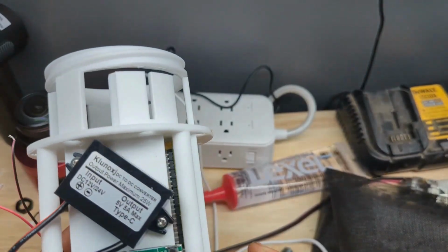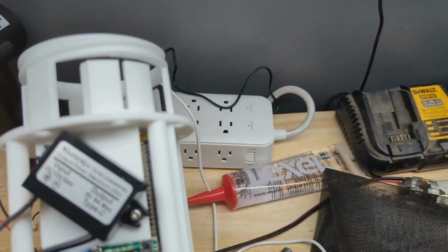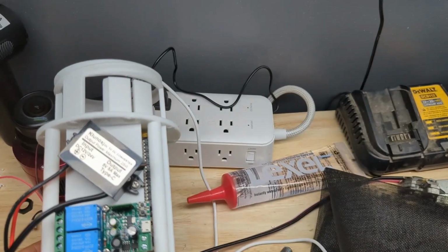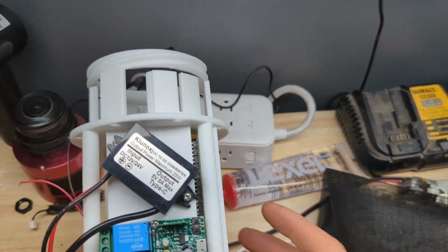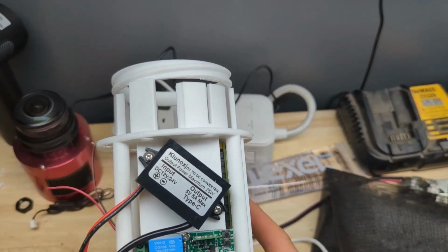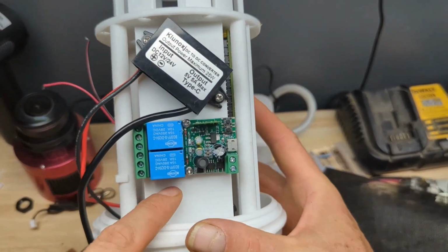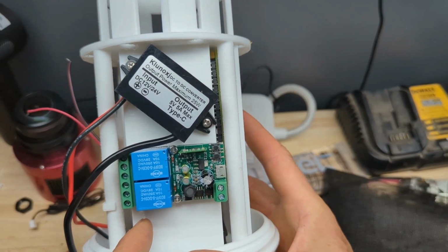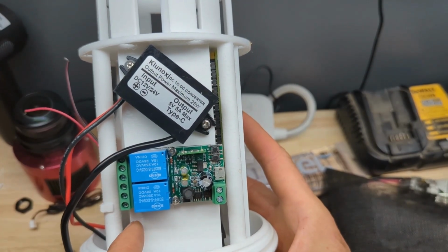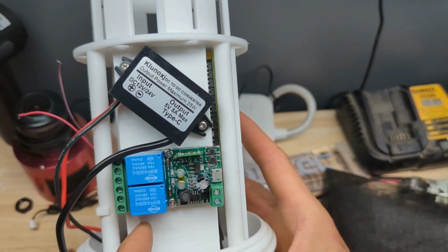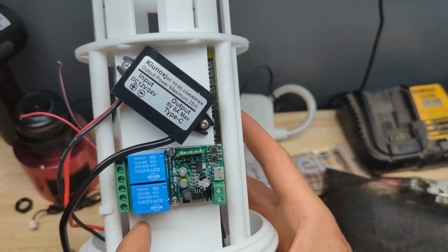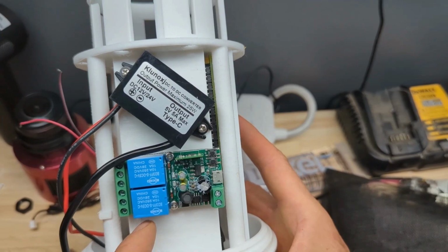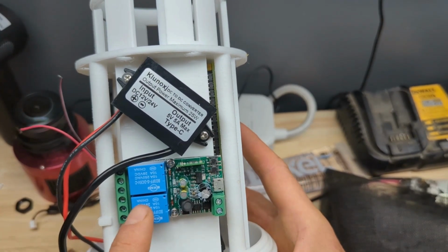And I will mention, I forgot completely to mention this a while ago, whenever you're tapping your holes, use a drill. Don't try to force the screws. Don't just start trying to make your own holes with a self-tapping, because this filament is plastic, and it can be like wood, and it can split. So if you're too close to the edge and you try to force a screw in, there's a good chance you may crack that out. So go ahead and use a drill to drill your hole, and then use your M2 thread or whatever type of screw that you're using for your components.